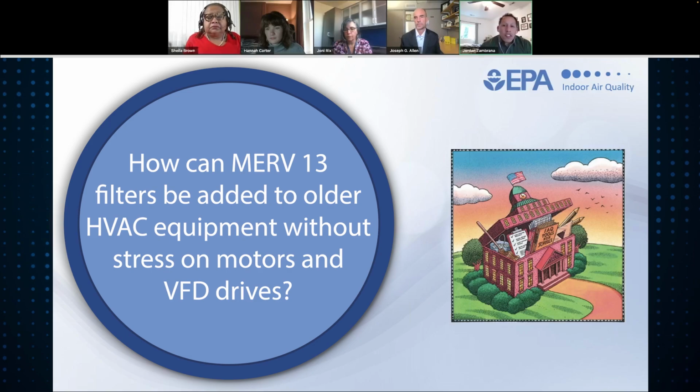Generally, we would not advise to just add MERV 13 filters ad hoc without evaluating what your system can handle. And we would say definitely consult with a professional when deciding what your system can handle.